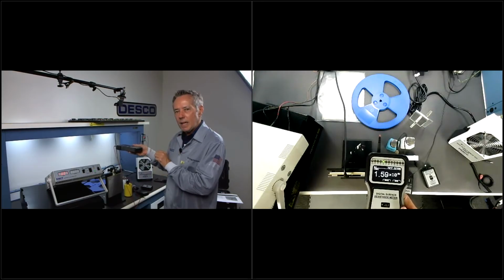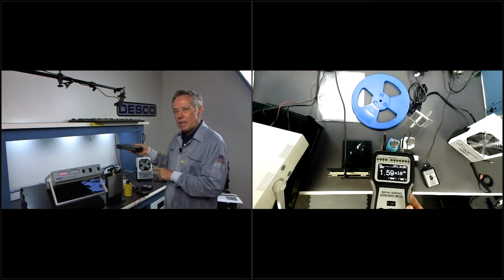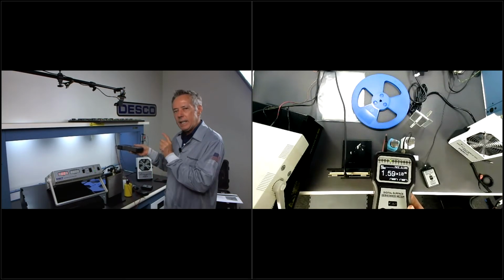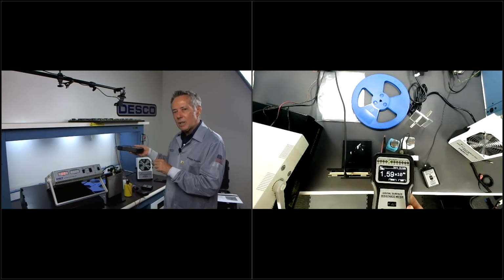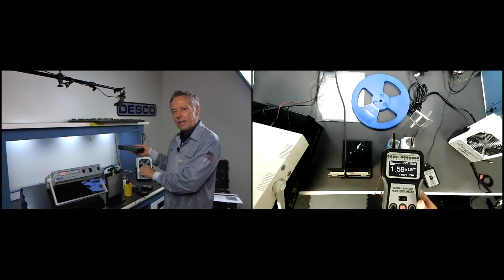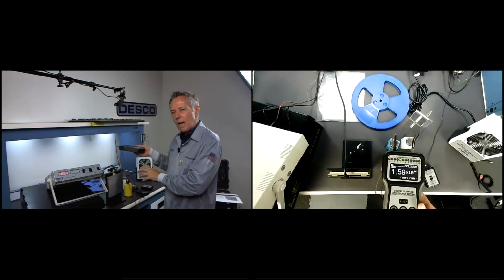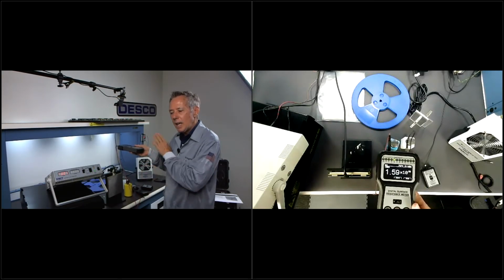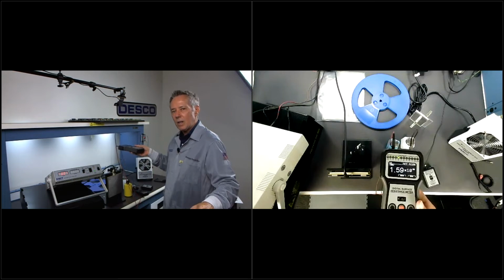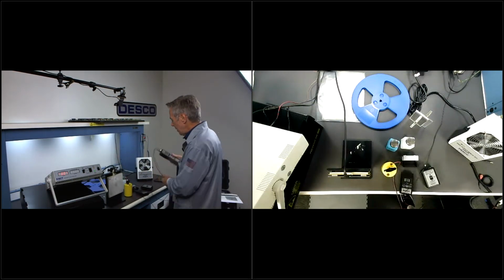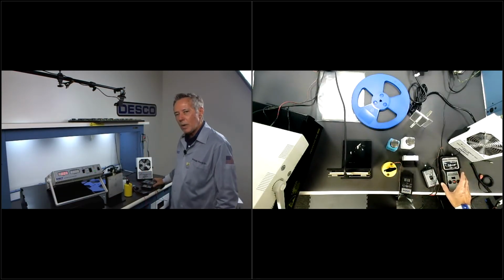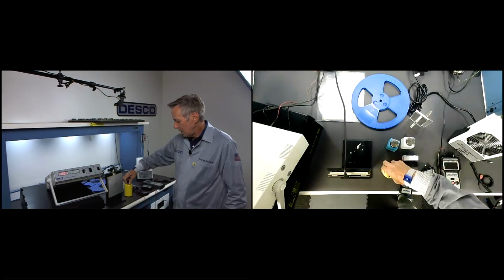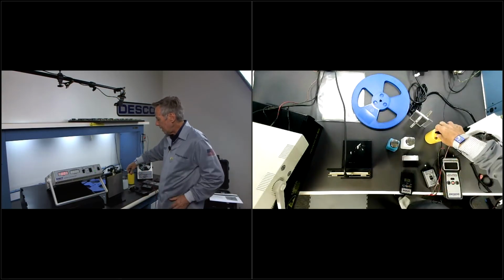The importance of this is, one, I know that it meets the manufacturer spec. I know that it meets the ESD Association standard specifications. And I also know that if I put a grounded conductor on this, it's going to ground that device. And if it has a charge on it, it's going to safely bleed that charge to ground. So that's the importance of this test. Whether it's an ESD chair, an ESD cart, my flooring, whatever it is, you need to know the surface resistance of your groundable materials.